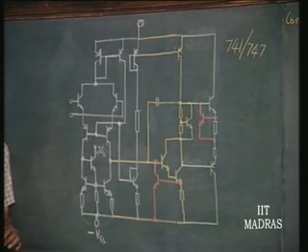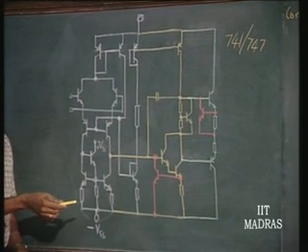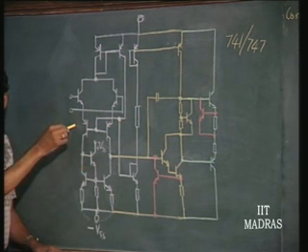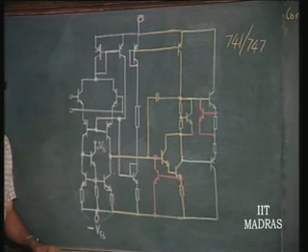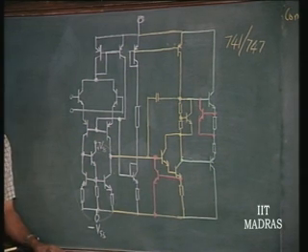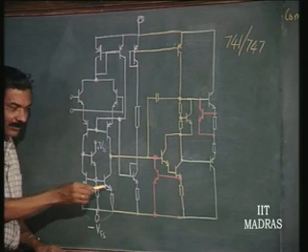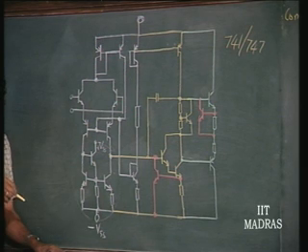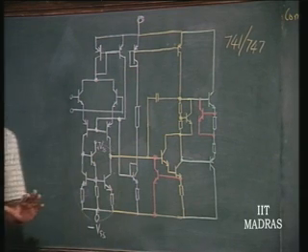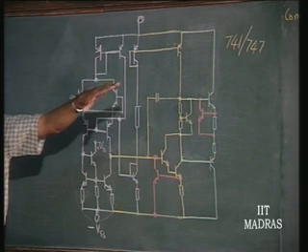Let us now discuss this. If these resistances are equal, because of the transistor mismatch, these two currents will be unequal. If these two currents are unequal, okay, even when the input signal is 0, there will be an input current into the next stage. If there is an input current to the next stage, automatically the DC current that we are talking of, output is going to saturation, right. So, in order to reduce the output offset, one technique of compensation is to make these two become unequal in a direction such as to compensate for the mismatch. Is this clear? So, I am now introducing two unequal resistances here, R1 and R2, okay, to make the output offset go to 0.